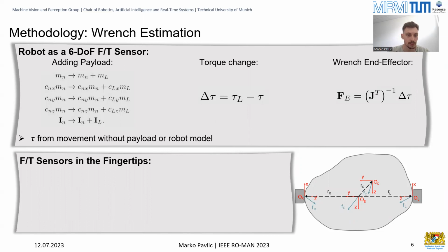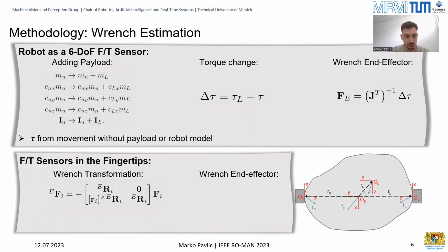In addition, we equipped the fingertips of the robot with force torque sensors, and we can transform the measured forces Fi into the end effector frame. And by summing all the measurements, we can also estimate the wrench in the end effector.